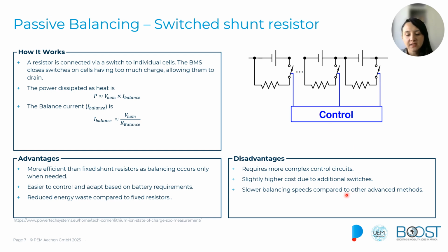But still, if we compare it with active balancing, this passive switch resistor balancing is cheaper, and on the other side, it will take longer time to equalize the battery cells.